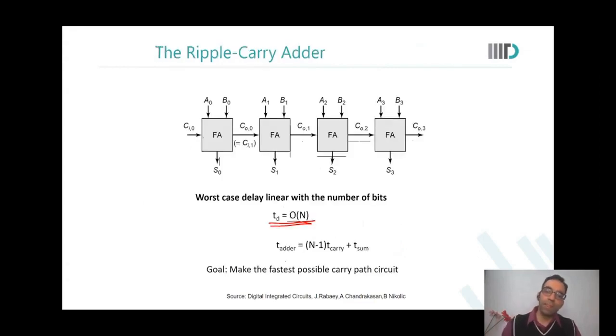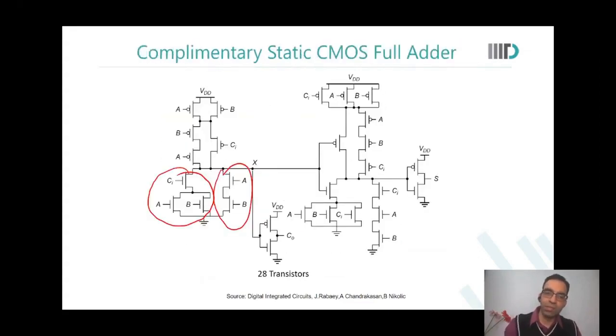Okay. So there is a different delay for generating a carry. That is evident because the delay to generate a carry is this path. The delay to generate a sum is this path. Sir, this sum depends upon the voltage at node X, which is also one of the inputs. So it constitutes this entire path from X till S. So yes, that can cause more delay for S than C out.